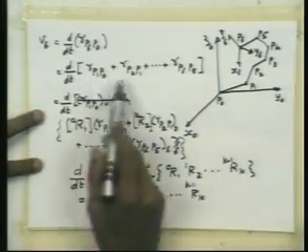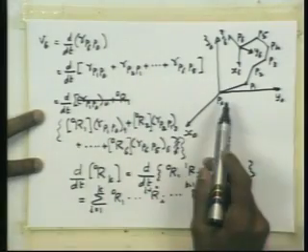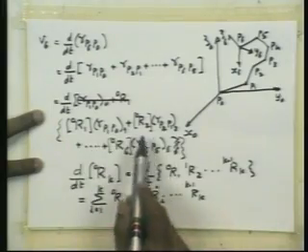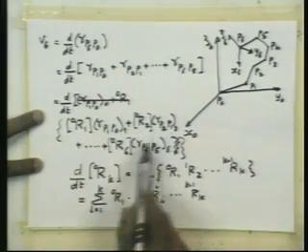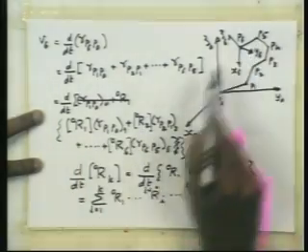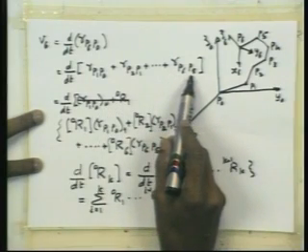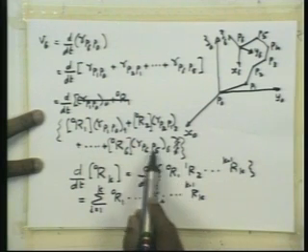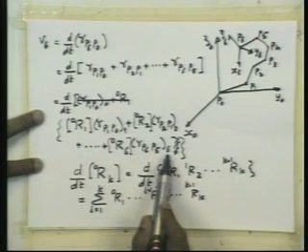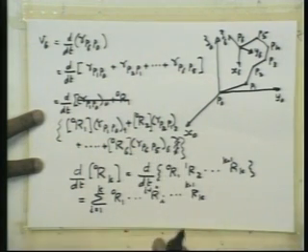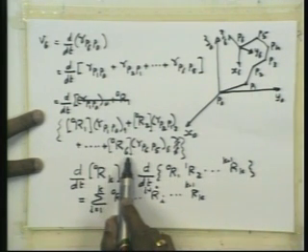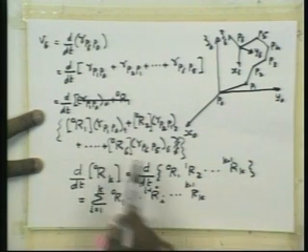So now these vectors, since they are represented in the global reference frame, they can be expressed in this fashion. For example, P5 to P6, that is the vector P6 with respect to P5, can be obtained from the local, the 6th reference frame representation of that vector, pre-multiplied by the rotation matrix which takes any vector, free vector, from the 6th reference frame to the 0th reference frame.